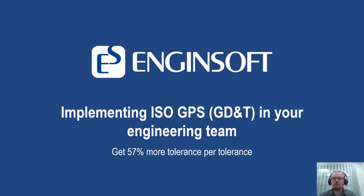This is very similar to the single standard for geometric dimensioning and tolerancing, GD&T, on our title slide there, which is what the American Society of Mechanical Engineers calls it. Both standards are very similar. They use substantially similar symbology and have many of the same ideas and cover many of the same topics, but there are small differences in many of the definitions between the two. So I'd always recommend referring to the relevant standard if you're doing drawings in either of them.